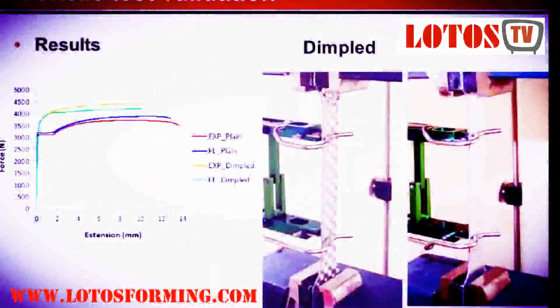The other validation, and also to show how good the simulation is, is that we perform a tensile test on the dimple strip produced from the dimpling process presented earlier. In this case, the dimple strip is put into the tensile test system, and we use an extensometer to measure the strength.